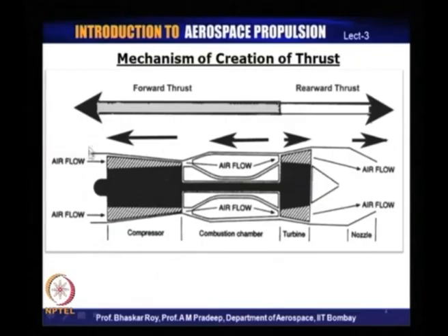And our understanding that the momentum difference between here and the end station, last station here, gives the thrust is essentially a concept. It is a very handy and convenient way of estimating the thrust, quite often reasonably accurate. However, a more accurate and more detailed measurement or estimate of thrust can be obtained only after we have all these components rather accurately determined, and the final value of the net thrust from here should be pretty close to the estimate that we had made earlier on the basis of net change of momentum.